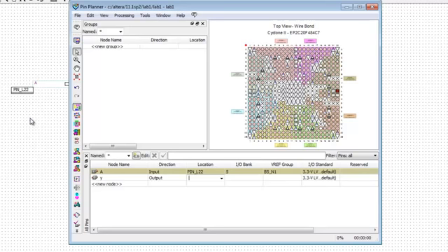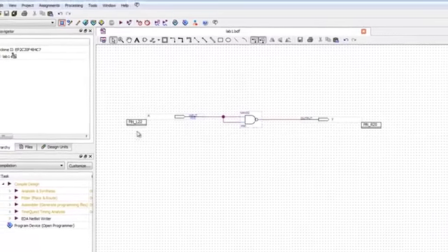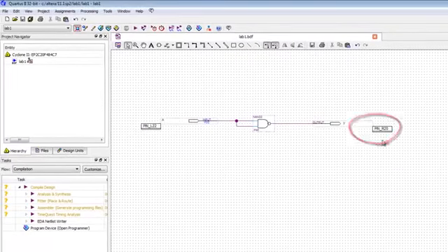on our circuit diagram. So now I'm going to go here, and for the LED I'm going to choose R20. So I just type R20, it puts in the rest, and I hit return. Now when you're done with your pin assignment, you don't have to save. They're saved automatically, so you can just close the window. And you'll see that the pin assignments are now on the diagram. Now you're going to have to compile again, so I'm going to do that right now. Just hit the little play button.